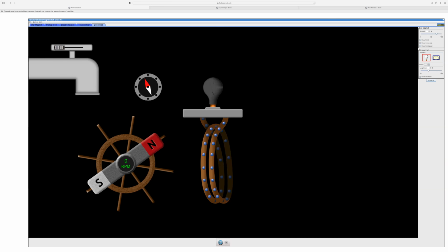You can do that, but what source do you need to use to increase and decrease? You don't know how many days it will work. If I give you an option of using a temporary or a permanent magnet, let's think of the real-time scenario. Let's say I'm asking you to design it such that my device works for 5 years. Which one will you prefer, a solenoid or a permanent magnet? Theoretically, you can do it, but you also need to look at the advantages.